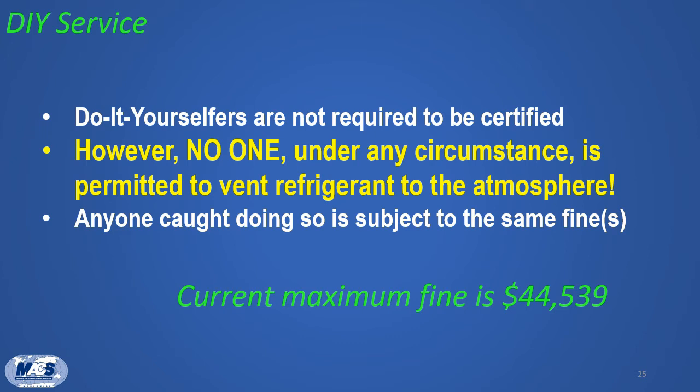However, anyone found to intentionally release refrigerant into the atmosphere under any circumstance during the repair, maintenance, or service of mobile air conditioning systems can be fined. This applies to any mobile AC refrigerant, not just limited to R12 or 134A, but also R152A and R1234YF. EPA assesses penalties for violations on a case-by-case basis based on many factors outlined in EPA's penalty calculation policy. And since January 31st, 2018, the Clean Air Act maximum statutory daily penalty is $44,539.